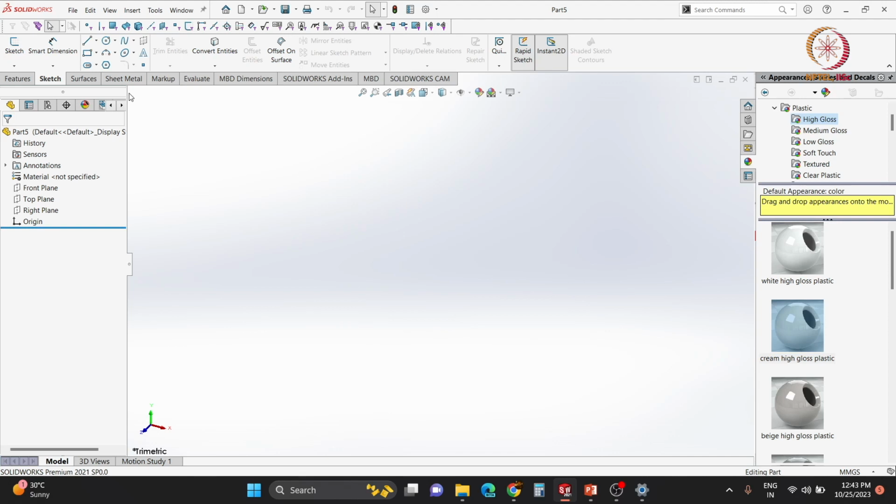First, the base of a 3D sketch is always a 2D sketch. So we will start by designing a 2D outline of what we need to create. Once we go to the Feature Manager, you will be able to see Annotations, Materials, and different planes. We can use these three planes to start building our 3D model, and we have the option to add an unlimited number of planes in our sketches. That is a slightly complicated topic that will be discussed later.